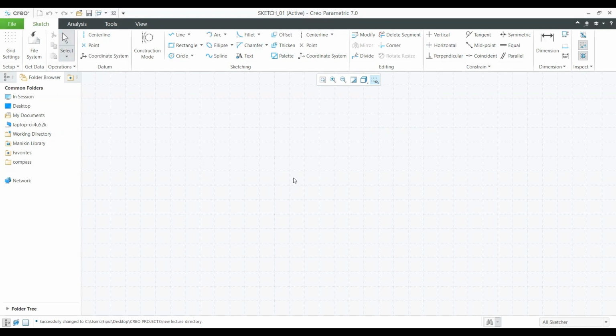So here, let's suppose you want to see the grid, you need to select this floating key. In this floating key, the last option is known as grid display. This is the display tab, where you can easily see the dimension display, constraint display, grid display, vertex display, and lock display. Let's suppose I don't want to see the grid display here. So I just unchecked it. Now see, my grid is gone. Similarly, if we want to see the dimensions, we can select it. But at the time we are going to create an object, we will go through it.